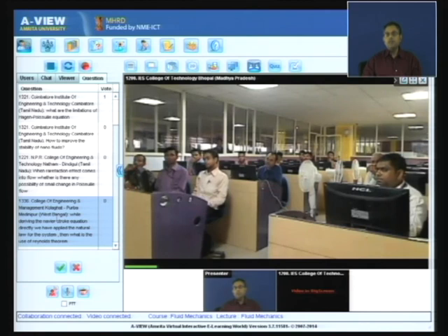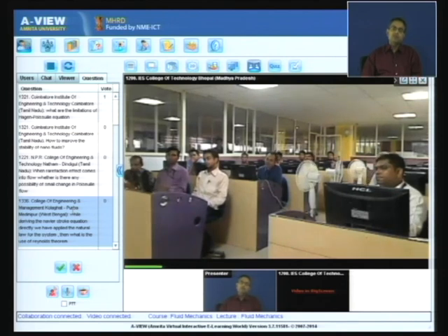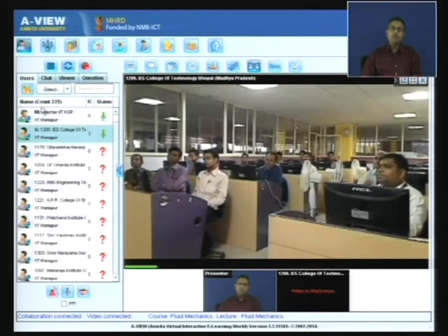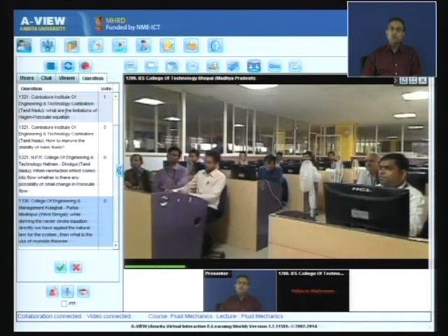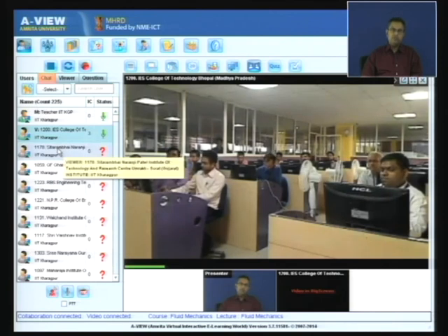So, one of the major assumptions behind the boundary layer theory is that the Reynolds number is large, and the second important assumption is that there is no boundary layer separation. That means there is no flow separation and no reverse flow. So, there are two major assumptions based on which you can apply the boundary layer theory: one, the Reynolds number is large, and the second, there is no boundary layer separation.